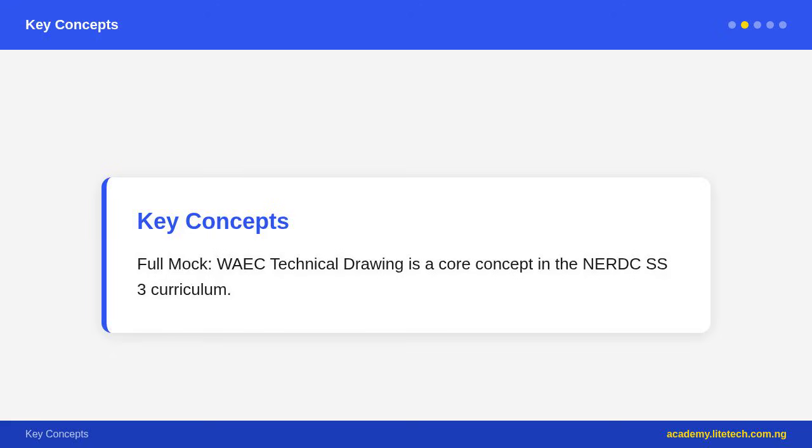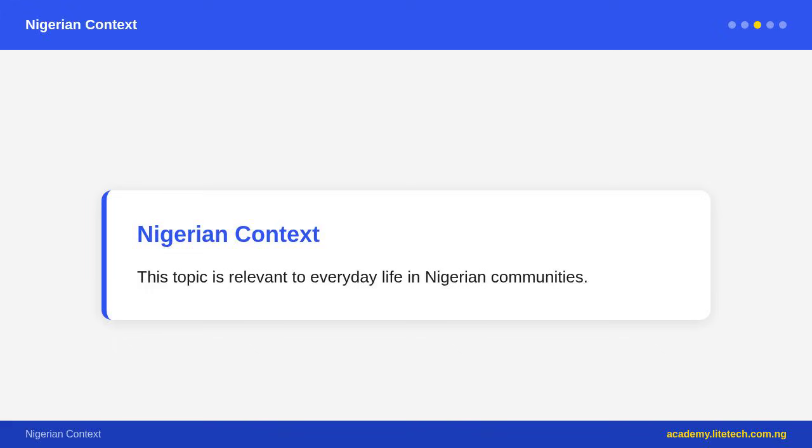Springs store mechanical energy and exert force or torque. Types. Helical compression spring, wound coil, compressed to store energy, pushes back when released. Used in vehicle suspension, ballpoint pens, valve springs. Helical tension spring, similar but pulled apart, in tension. Has hooked ends.